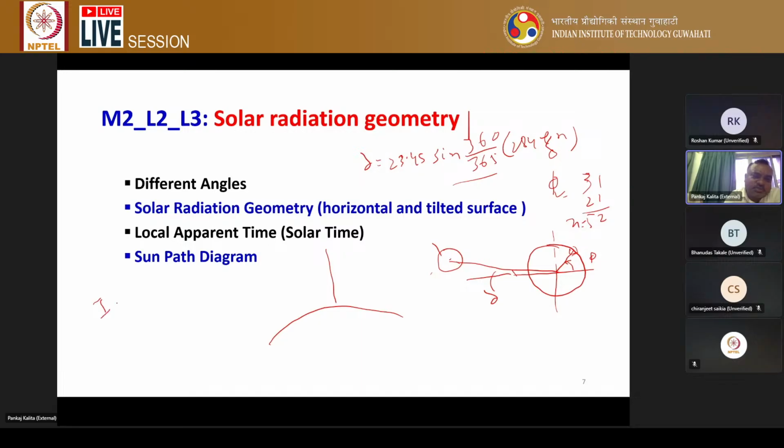So sometimes we use IG, the global radiation. This is instantaneous, I can say. And if we place a bar on it, then it becomes average hourly global radiation. Okay, so Klein is a researcher who has recommended some dates of a particular month which give the representative data for the radiation.